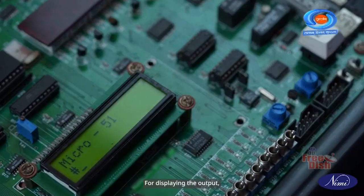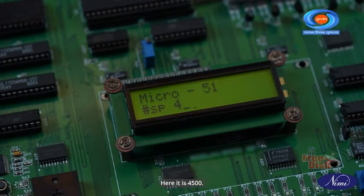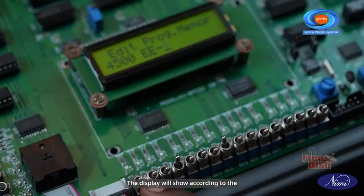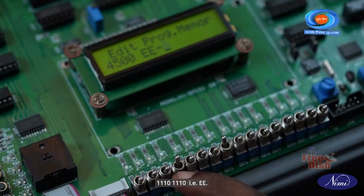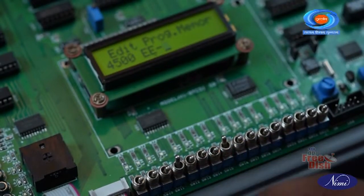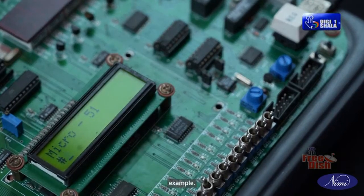For displaying the output, enter SP and the data pointer address as we stored the value in it. Here it is 4500, and click enter. The display will show according to the switch's condition. Here it is 1110, that is EE. Click reset button to execute another example.